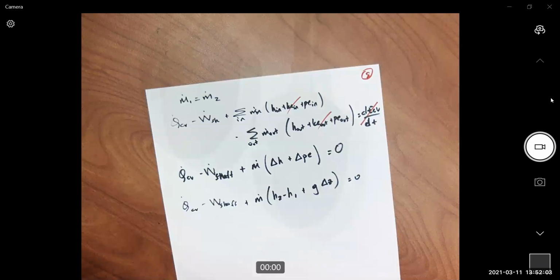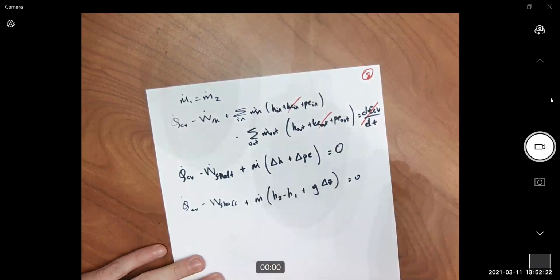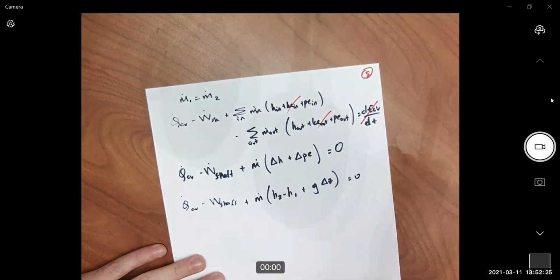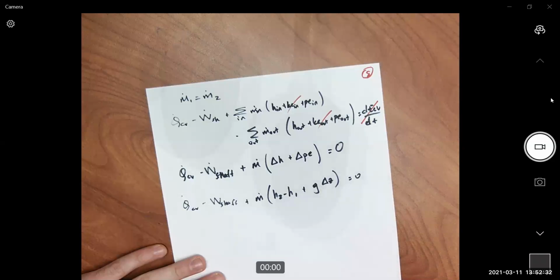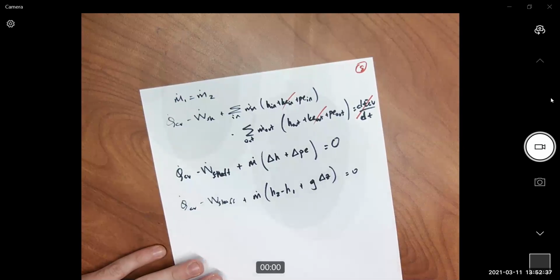Okay. It says that temperature and pressure difference are 0. There's no significant change in temperature and pressure. It means that your property stays constant, so delta h here is 0. We can also prove that by reading the table. I will leave that to you, so make sure you do all those steps. Assume you have a compressed liquid, water.